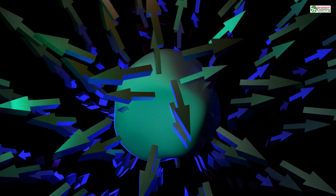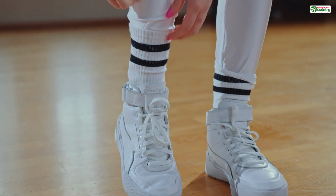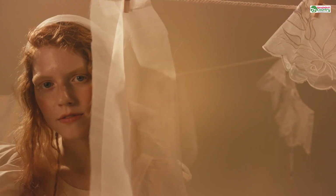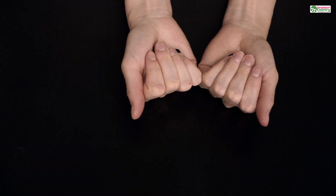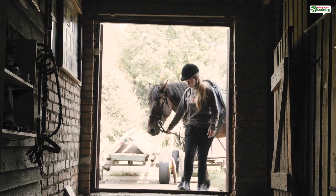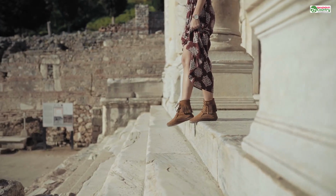The best analogy is a t-shirt. When you wear it normally, the outside is facing out. But if you put it on inside out, the seams and tags are showing. The fabric is still there, the shape is the same, but its surface is fundamentally facing the wrong way. When a slicer sees a flipped normal, it thinks that part of your model's skin is inside out. It interprets that area as a hole, a void, a negative space, even though the geometry is perfectly connected. This can lead to entire sections of your model simply vanishing from the final print, as if they were never there.